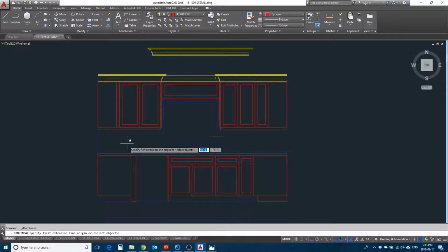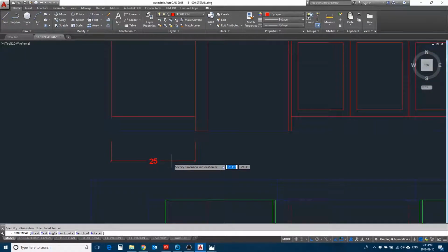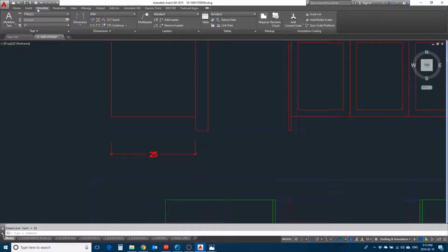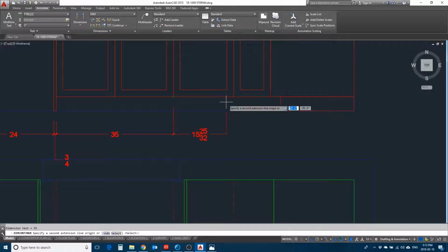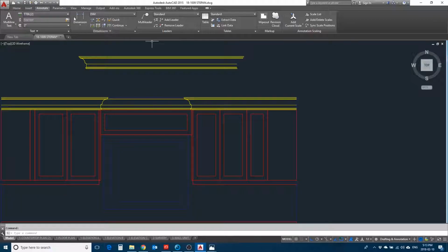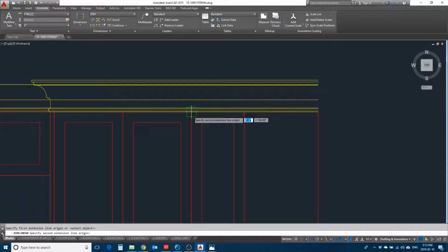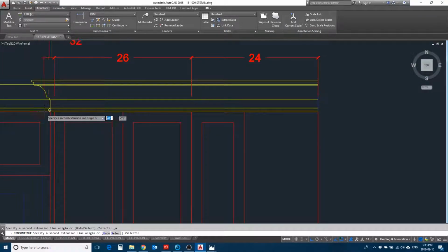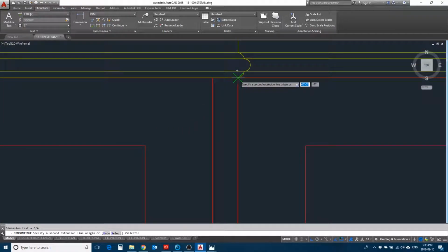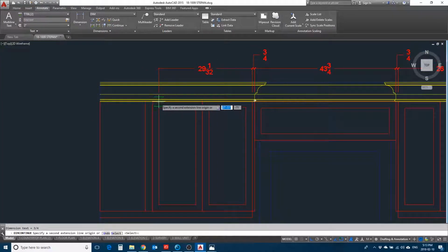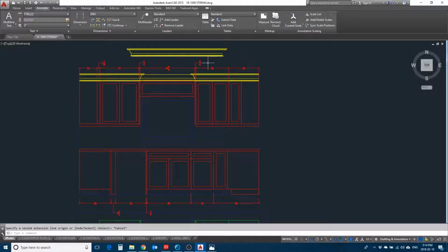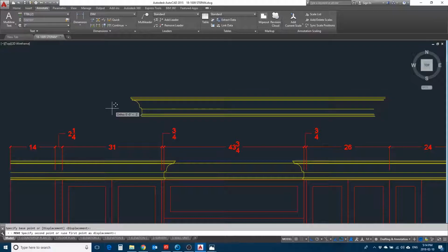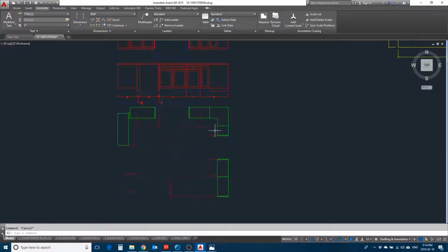And then we go dimensions. So this is 25. Annotation continues. We have a 3-inch filler. 35, 18 inch, this is going to be a garbage, and that's one single cabinet. So we have that done. Now we do dimensions here. So that's a 24 by 24 inch cabinet. Continues. Check. So that's done. This we could move, M, move it up. So this elevation is finished.